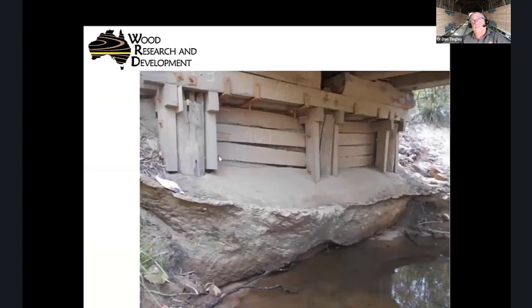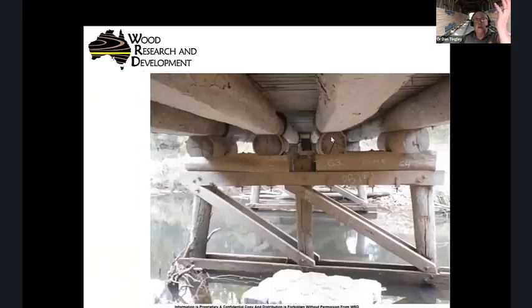This is a bridge called Running River, where they did everything wrong they could. They encased it in concrete, spiked the approach sheeting planks, each one of them to the pile, which you don't do. You let them settle on one another. You had piles that were braided at the top, completely cavitated. They put these T's underneath them, and the top bolt picks up 80% of the load, and then it cleaves. And the whole thing was a mess.